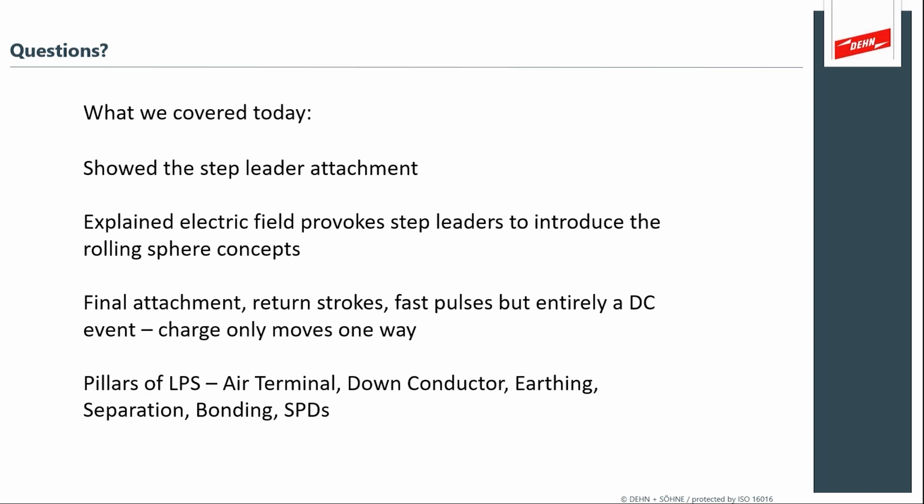Yeah, that's a really good point, Stephen, that the IEC standard indicates not only the low end of the lightning content. If it's a baby lightning stroke, for instance, it might have a small rolling sphere, but it also dictates the high end of the amount of current that might be present in the lightning bolt.